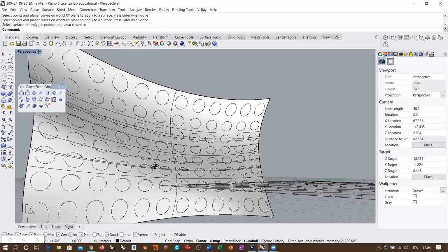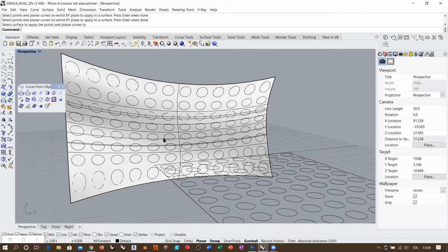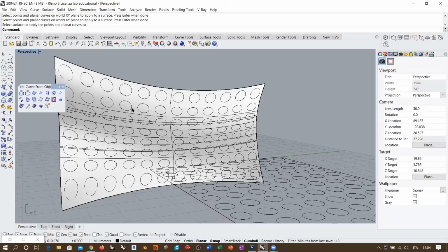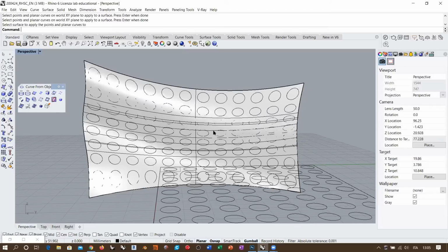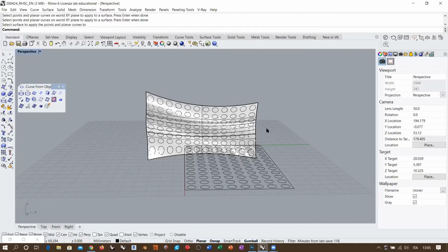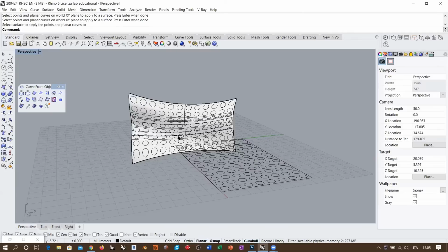Now, I get this distribution of circles, but you see that I have vertical ellipses and horizontal ellipses. This is due to the speed of this surface vertically. From the longitudinal aspect, we have a smooth, even distribution of spans, because we were using only 1, 2, 3 cross sections, which are more or less with the same separation. So you see that the width of this circle is not changing, but the height changes according to the topology, okay?